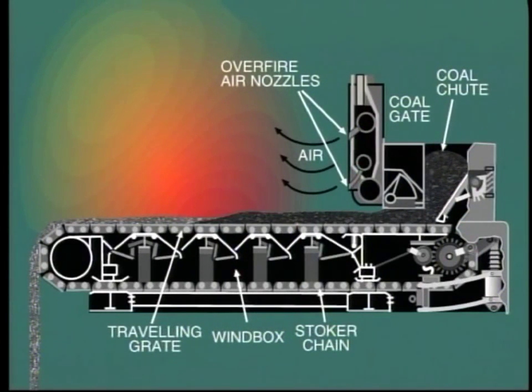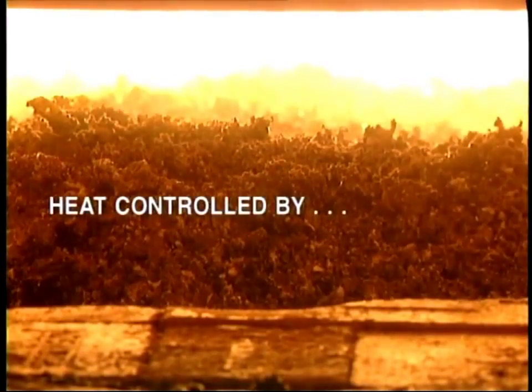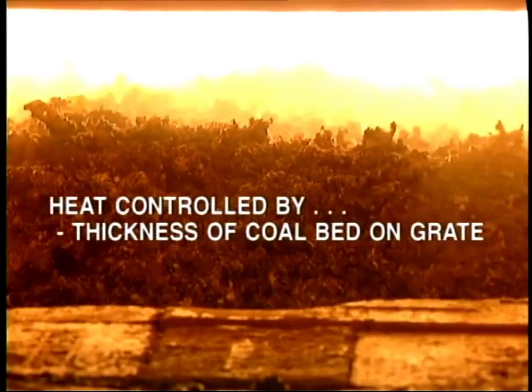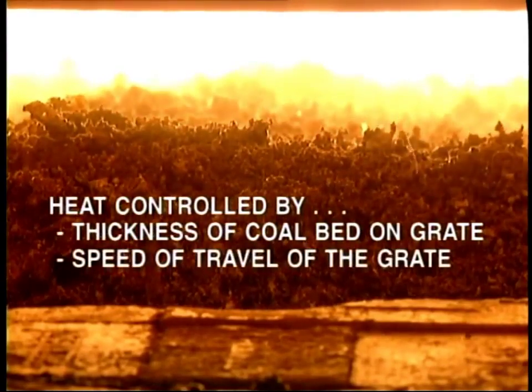As the grate continuously moves forward, the coal on the bed burns, leaving ash to be discharged into the ash pit, as the grate follows its continuous path and returns again to the coal feed. Control over the heat input to the boiler and consequent steam output is effected by adjusting the thickness of the coal bed on the grate and the speed of travel of the grate. The correct distribution of air is vital if complete combustion is to be obtained.